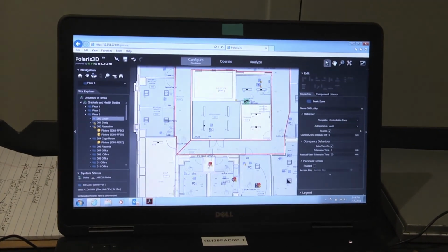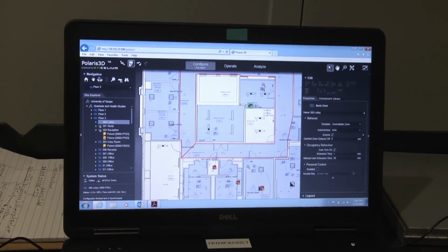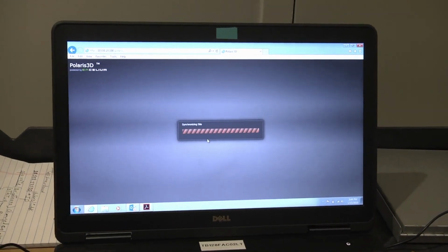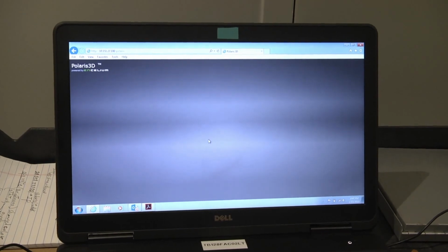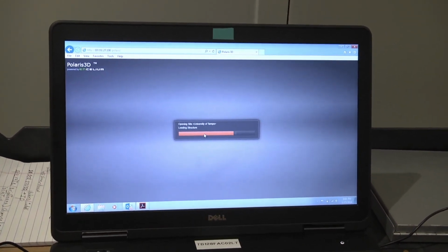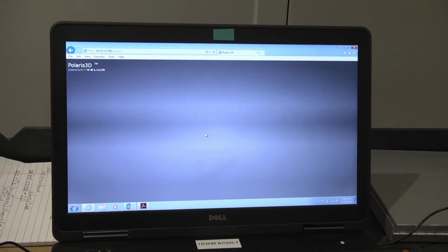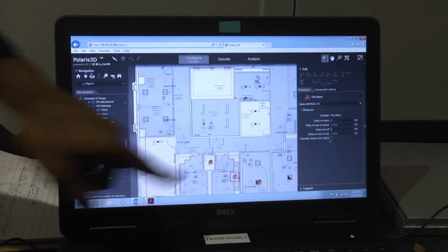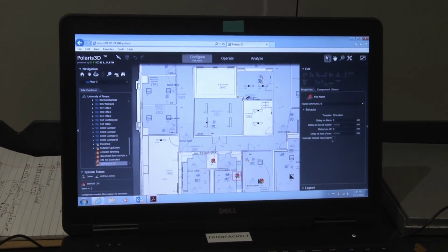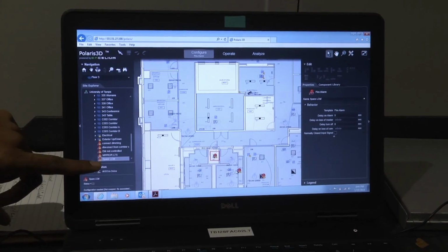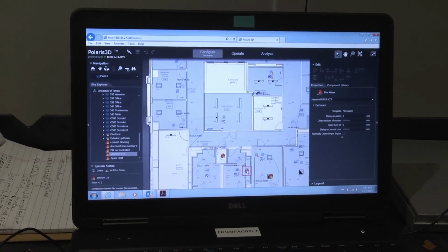Let's see, close that. You don't need to configure at this point. You can save it because you're not really sending any instruction to the ECU. You're just making a note that something is there. So saving is fine for now. See that delay alarm. You can look and see the notes that are showing up to the side. That's the one you just created a while ago, Spare LCM. Mirror lights.